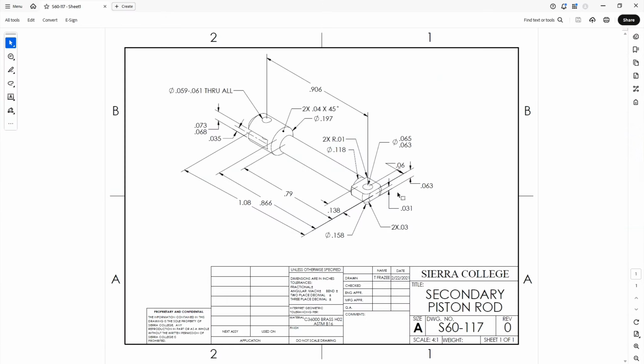And we have two different fillets. We've got a fillet called on the outside of an R 30 thousandths. It falls in two places because after we revolve this, it's an interrupted cut. So it's two different places, two corners. And then in two places we have 10 thousandths fillets here. Let's go put those in.